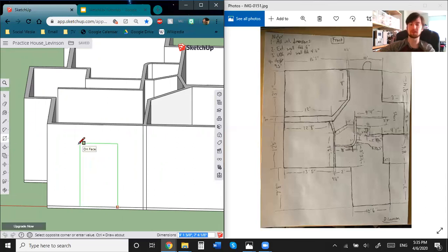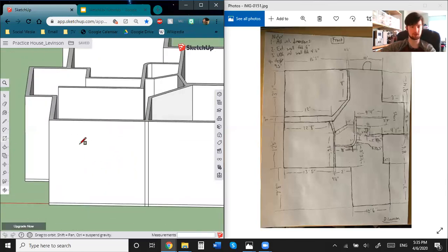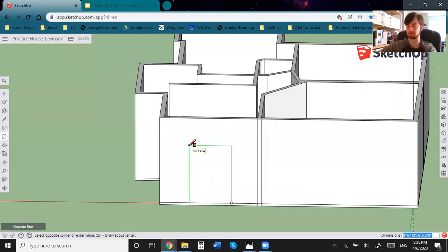I think for most of them, what I'll do is I have 2 outside doors. Those 2, I'll measure them to have a width of 32 inches, as you see in the bottom middle, where it says dimensions. And you know what? I can actually make this full screen now. We don't need the floor plan anymore. So now you see bottom right, 32 inches, comma, and I'm going to make this 7 feet tall. I'm going to make all my doors 7 feet tall. So 32, comma, 7 feet. And I press enter, and there we go.